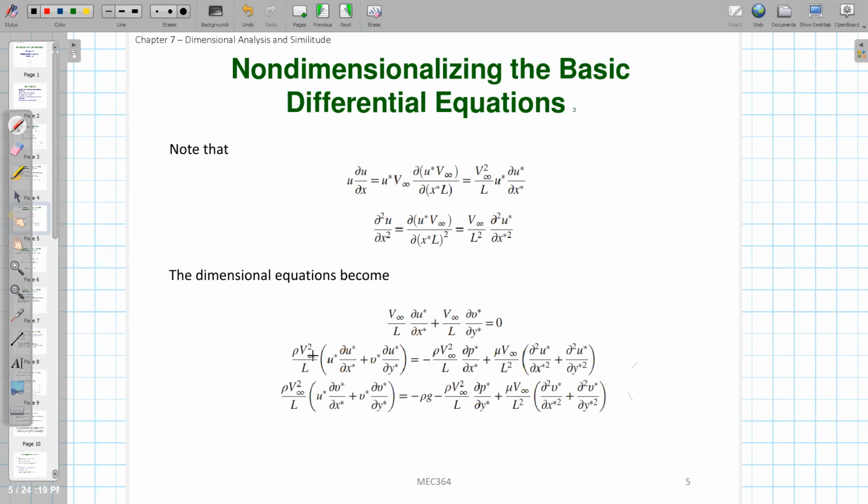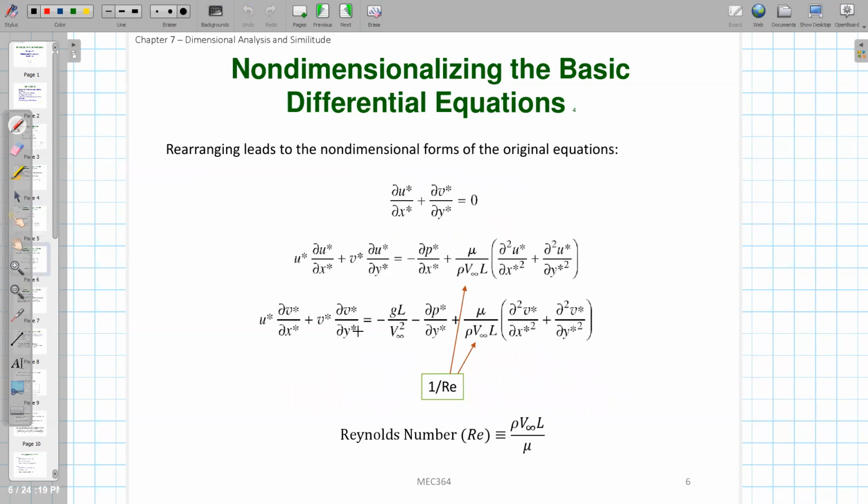Okay, for the momentum equation, on both sides you divide by this constant term. Rho is constant because for this problem we assume incompressible flow. So you divide this term on both sides, and your momentum equation will become what? It will become this form for the x direction momentum and the y direction momentum. And this is the continuity equation, right? We already showed you earlier. So this is called the non-dimensionalized governing equation, the non-dimensional governing equation.